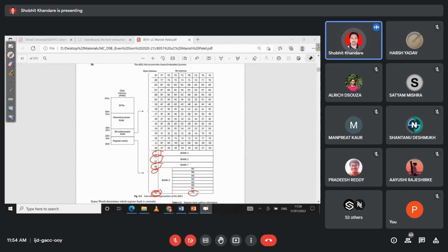ओके, अब ये देखो आपका ये हो गया रजिस्टर बैंक. ये पूरा एरिया है रजिस्टर बैंक का. तो कैन आई से इट इज फ्रॉम 00H to 1FH. आपका 00 यहाँ पे है और आपका 1F यहाँ पे. ये हो गया. अब बिट एड्रेसेबल की बात कर रहा हूं. ये देखो बिट एड्रेसेबल. बिट एड्रेसेबल कहां से कहां तक है? It is from 20H से लेके 2FH.